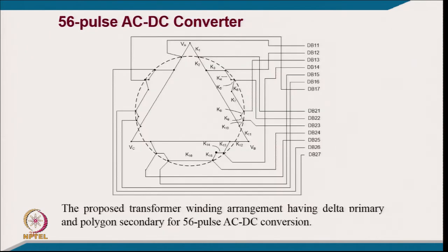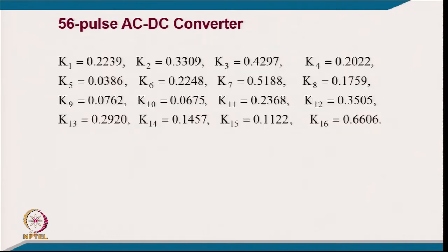And these again are auto connected transformer connections. You have an input supply, but the output requires 2 sets: 1 set of 7 phase and another set of 7 phase, which are converted from the 3 phase input supply. They have a symmetric 7 phase, and this is another symmetric set, but between the two you have the interface. All these voltages should lie on a circle, so that you have all equal phase voltages with respect to the transformer. Even if the input voltage is more or less, you can design accordingly.